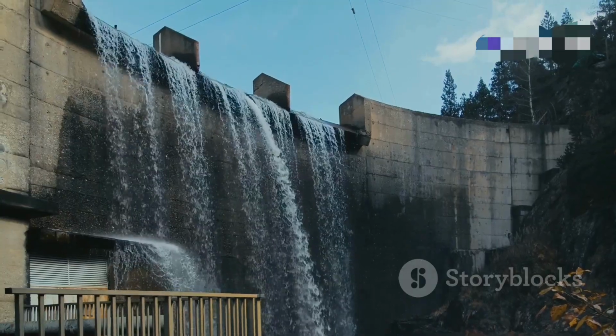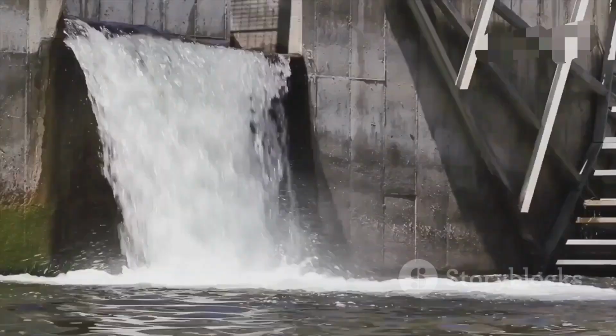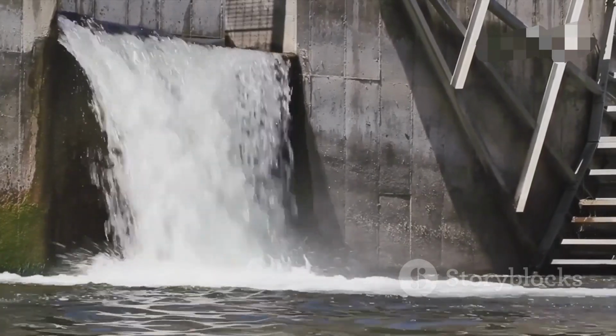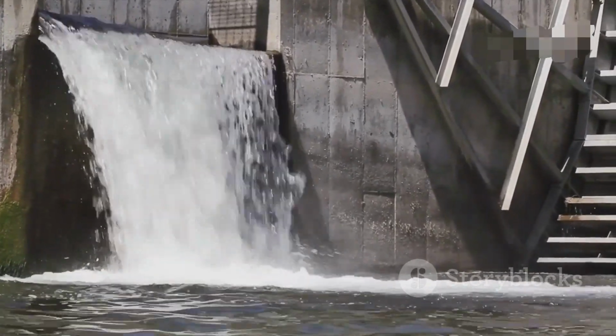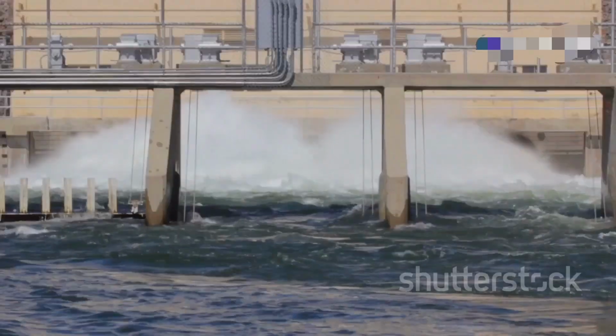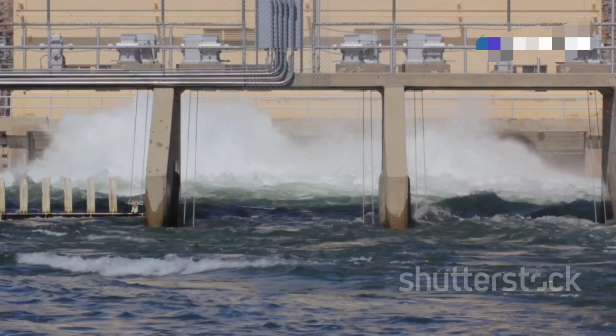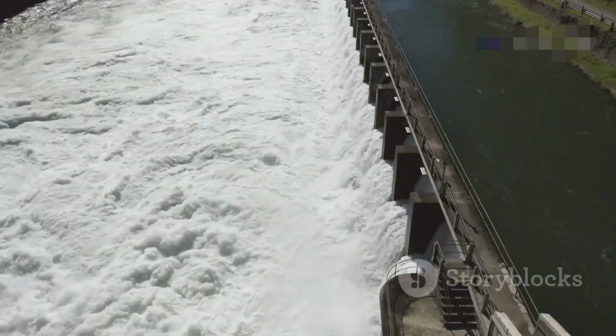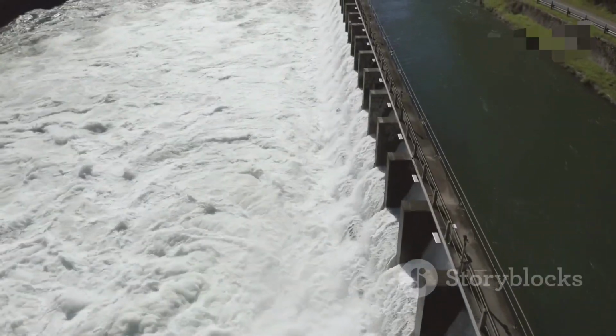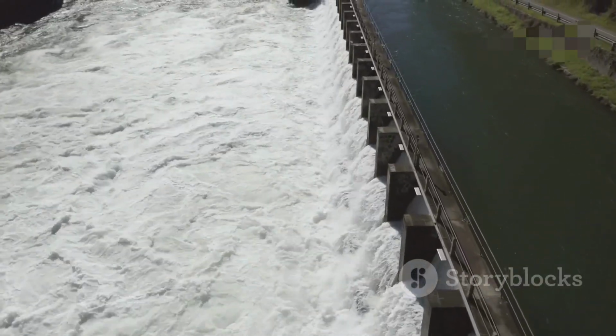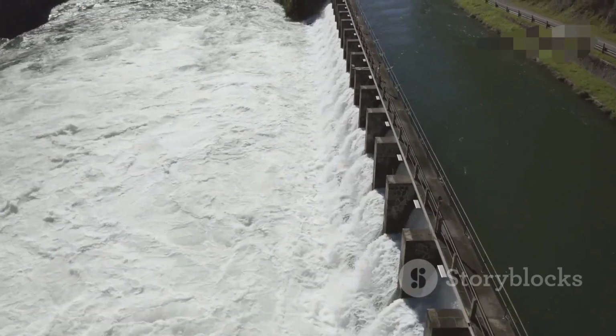These structures are much more rigid than earthen dams. Failure might begin with the instability of one or more monoliths, which are the vertical sections of a gravity dam. This could be due to excessive water pressure, earthquake forces, or deterioration of the concrete or foundation. Foundation problems, such as excessive uplift pressures or erosion of the foundation material, can also lead to failure.